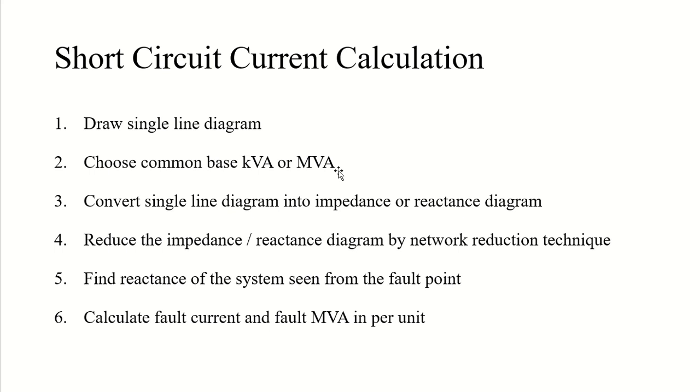Third point is we need to convert these single line diagrams to impedances or reactances, right? Basically you will be converting the single line diagram to impedance diagram or reactance diagram. We learned that as well previously. After that, we will use the network reduction techniques which I talked about a minute ago, and we will reduce this reactance diagram or impedance diagram using these techniques.